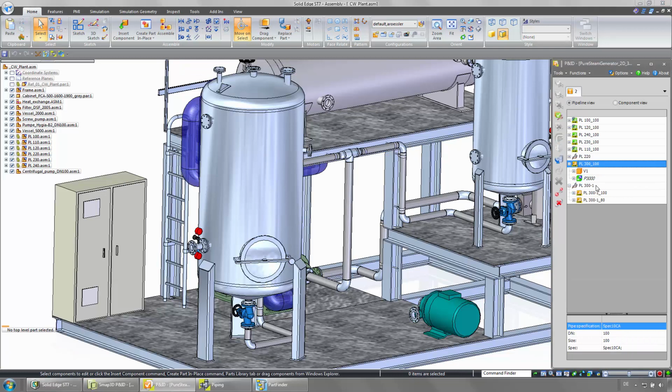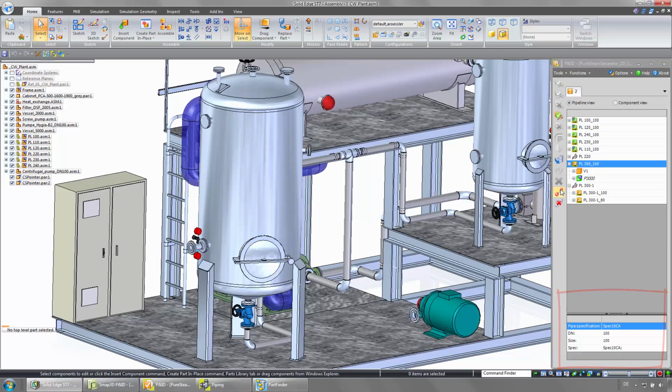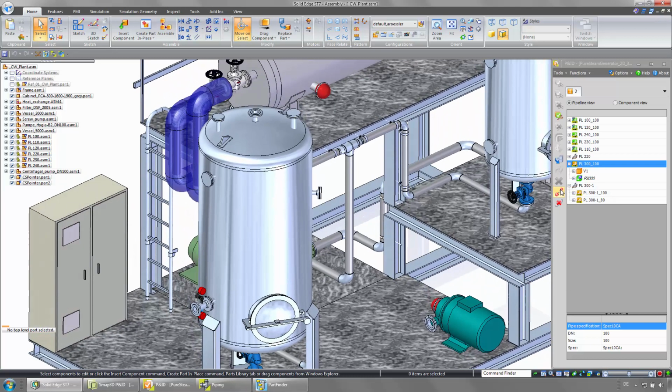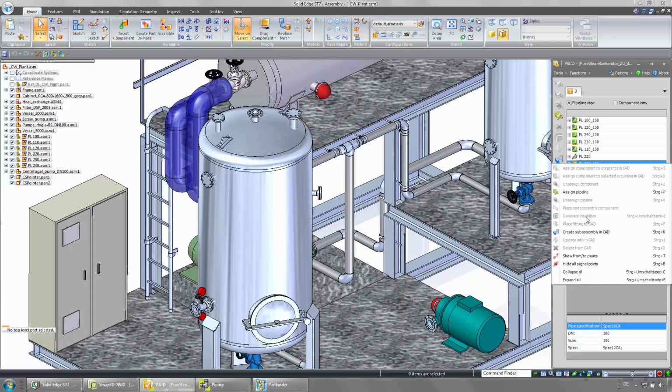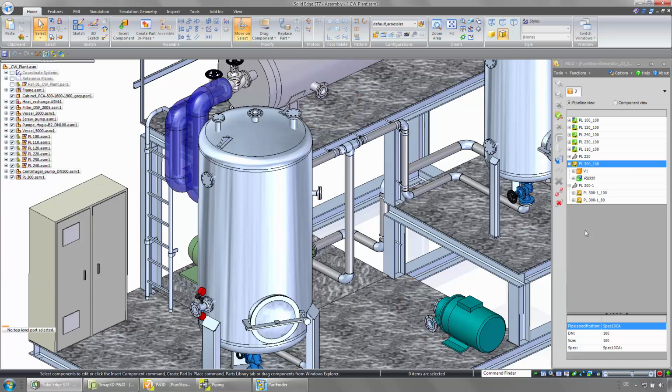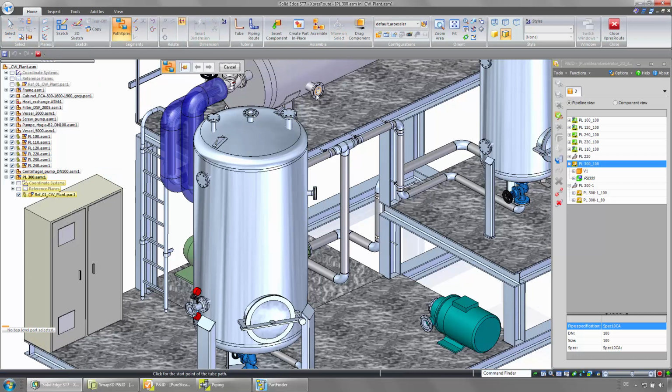With the information from the P&ID, the 3D pipes are ready to be created. The function FromToPoints helps the user find the correct connection points. After a subassembly is automatically created, we draw a 3D pipeline path with the Solid Edge Express Route function, Path Express.